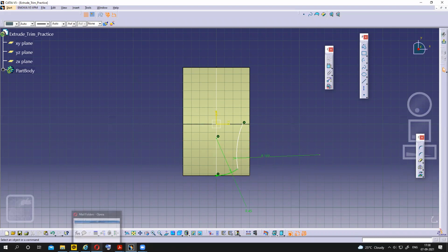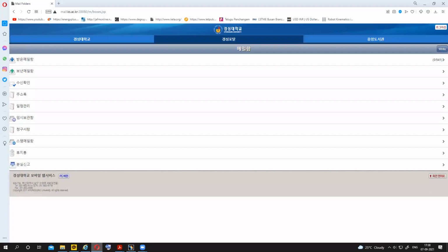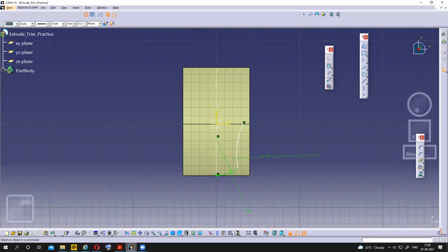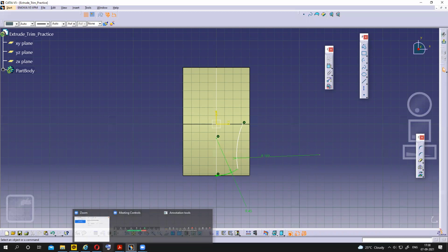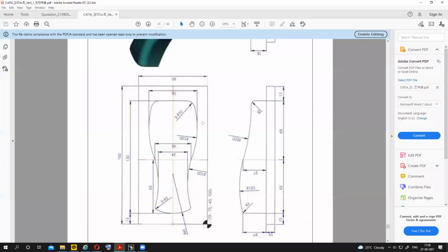And later you can give the 3 fillet, right? Fillet 3 now, or you can give that one later also. Here the corner, you can do it later also, and I am doing that one later. And now edge fillet, I give edge fillet. So next what I have to do, I have to make again this side. Okay, R100 up to here,